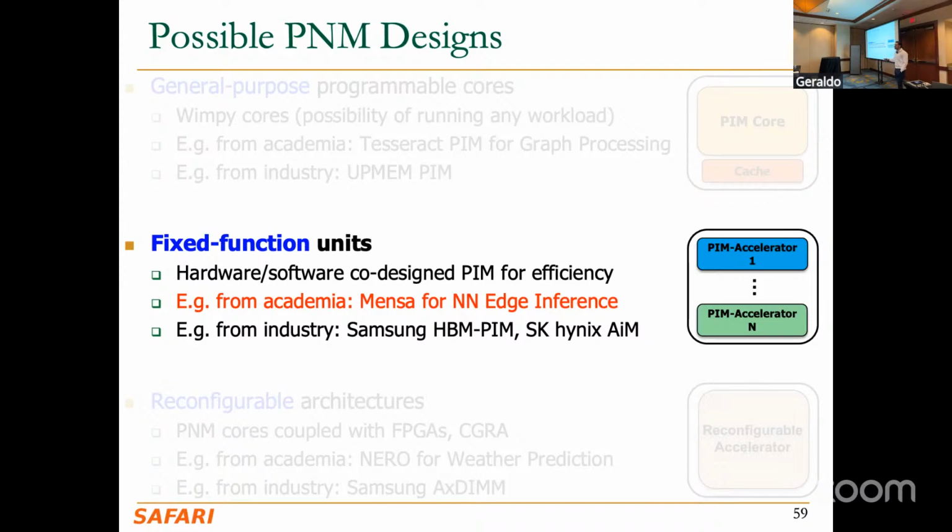So the idea here is that, as in GPUs, you can amortize that initial data copy of the input data by operating multiple times over that data. So basically, yes, you copy input and output out of that system, but there is still a bunch of intermediate data that stays inside the UPMEM chip, and you don't move the data back and forth, as long as you don't have to do communication across the DPU chips.